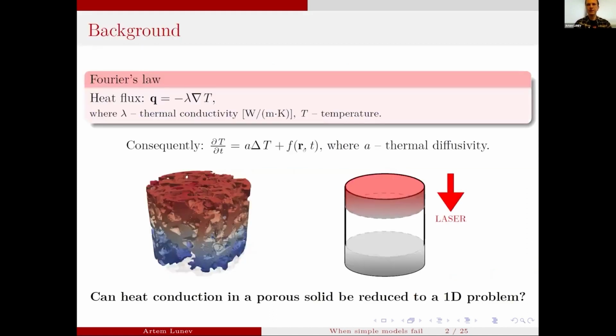So the background for this work is to prove that the LFA may be a suitable tool to study porous materials. The LFA is a thermophysical method based on the Fourier law. All conventional thermophysical methods are based on the Fourier law, which says that the heat flux is linearly proportional to the temperature gradient. The question that we posed here is, can heat conduction in a porous solid be reduced to a 1D problem?